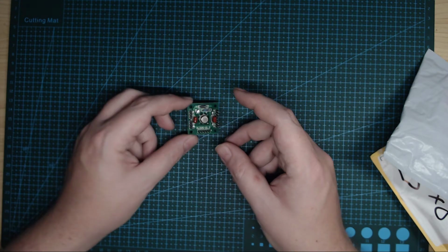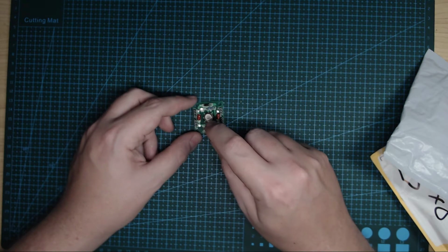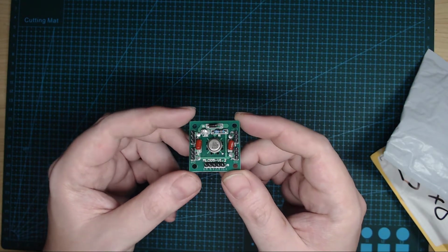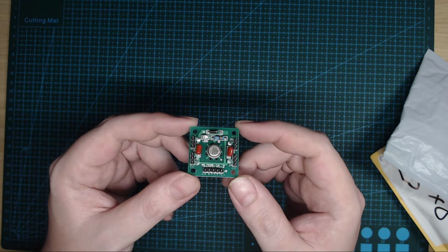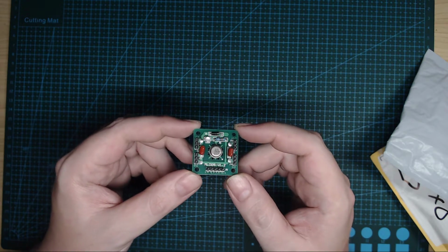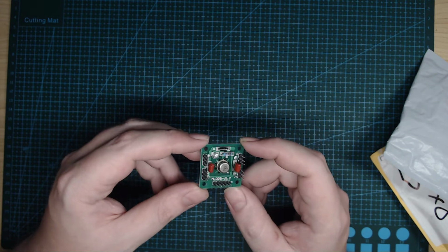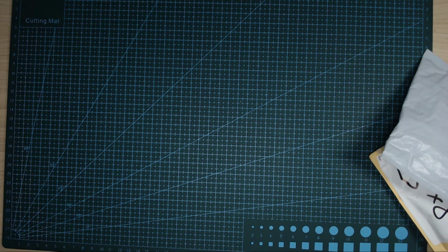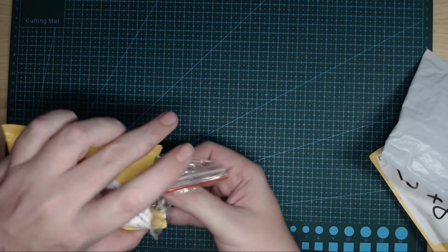But the good thing about them is that the actual voltage reference itself, they normally have a burn-in process or an aging process where you have to run them for 1,000 hours or whatever it is before you can actually trust their readings. And so, being that it's an old unit, it's already had that burn-in process done. So it's actually pretty much ready to go as is.